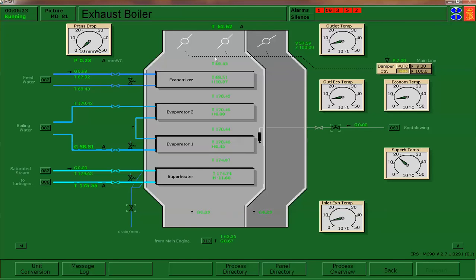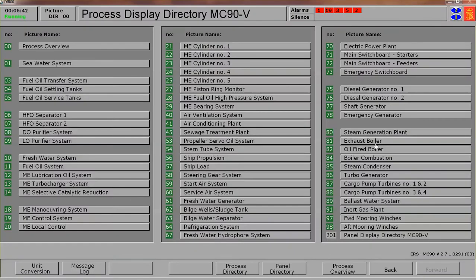with the exhaust gas boiler having flow through it. If we had a long maneuvering at a slow RPM, I would not do this because I'd be more worried about soot collection when at low volume. But we're going to have a fairly short maneuvering, so we're going to go ahead and open that up. Now I'm going to go look at putting on my steam turbine.